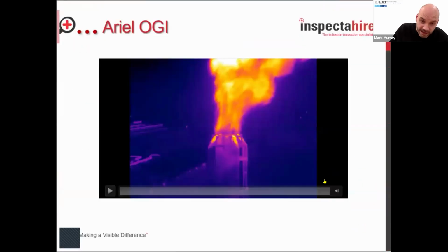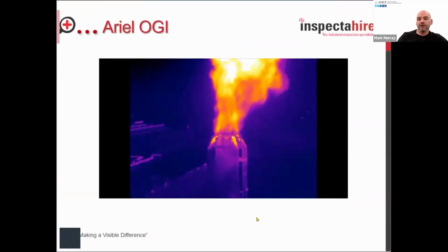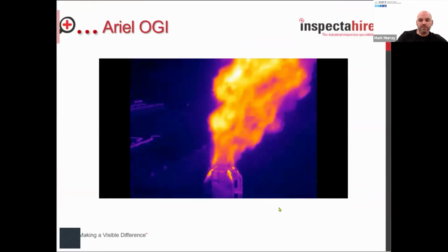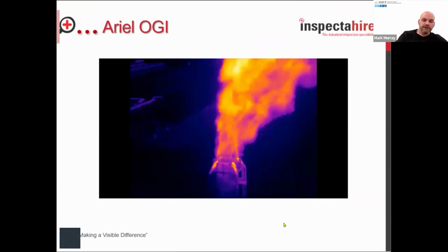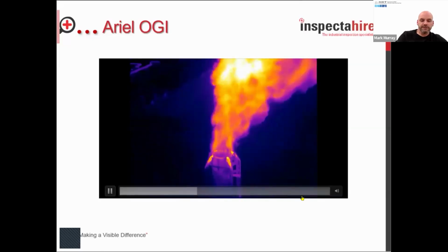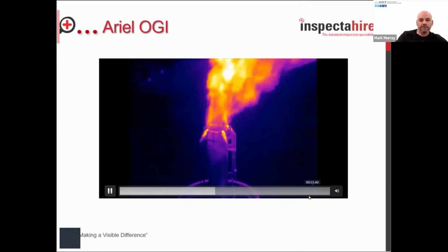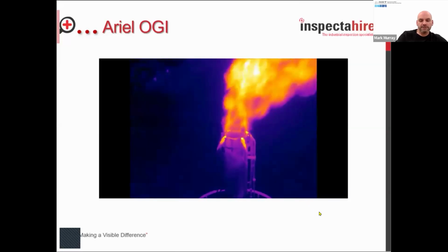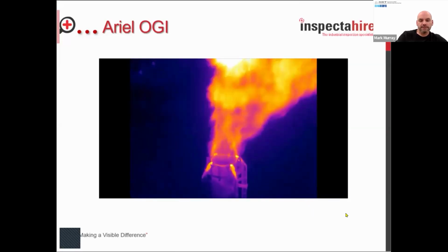So aerial thermography can also be qualitative. Things like flare burner temperatures are crucial to the life of the flare. If they're being overheated, then that can have a significant impact on the lifetime.